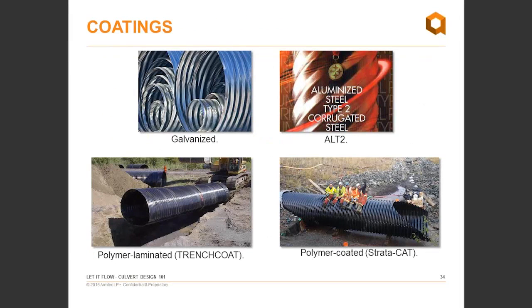We just had a couple questions come in from the previous section that I thought we might get to here. There was a clarification on Manning's N, and someone had mentioned they hadn't seen it applied to deep corrugated. Basically they were just asking how it was verified? That's a good question. For deep corrugated, it's an estimated Manning's N. It very often doesn't come into play because most deep corrugated plate are open bottom structures.